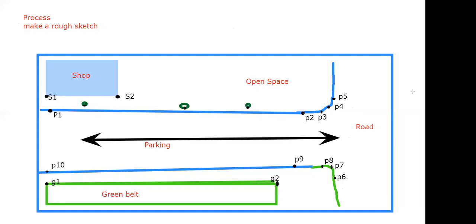Okay, so when you go out into the field with your survey book and with your rough sketch, you must have a piece of paper, and that piece of paper, or you can have a diary or a notebook or a copy, and that will be called as your survey book, and it will have two columns. Your survey book will have two columns.